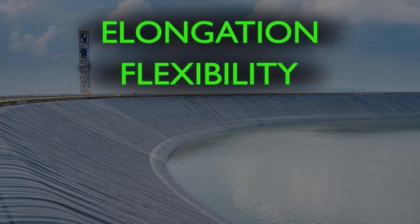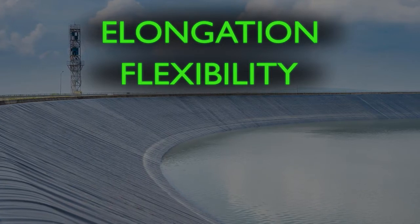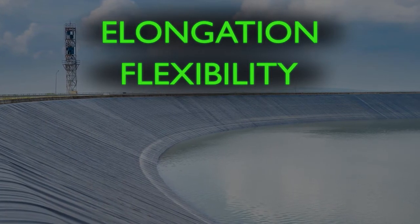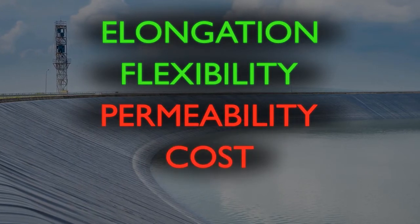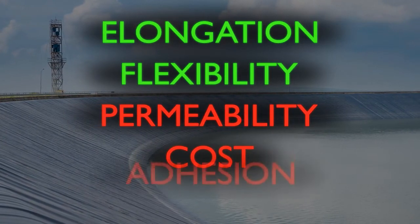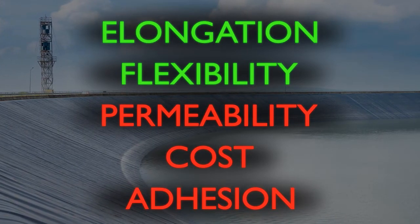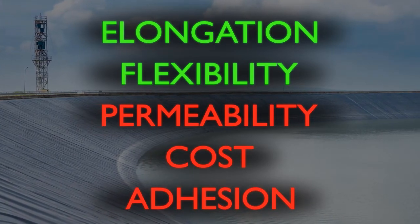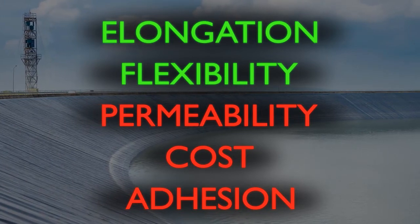This makes then a good choice where settlement is likely or where complex detailing must be undertaken. PP is, however, relatively permeable to most gases and is expensive. PP membranes also have poor adhesion characteristics, therefore require specialist welded joints rather than tape jointing. PP membranes are traditionally used in water containment applications, due mainly to its suitability for use on larger unreinforced areas.